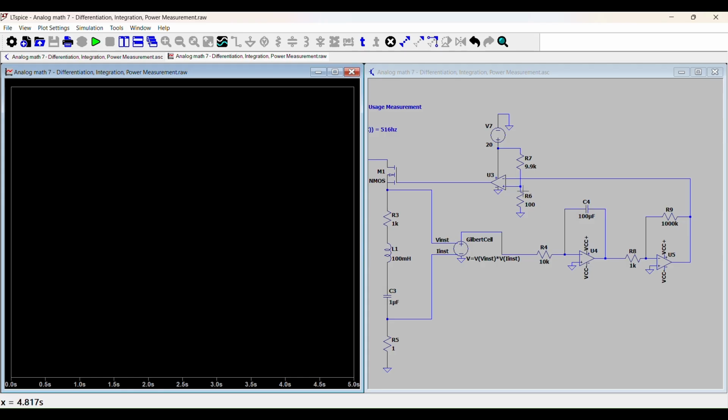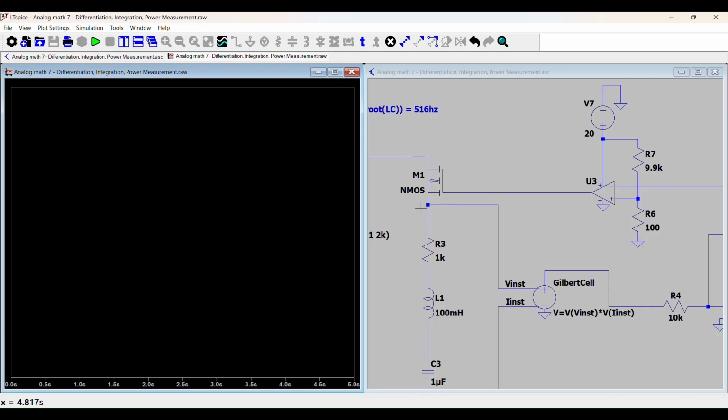You can do this with a much better thing than a voltage divider. You can use a potentiometer here to adjust it, or even a straight signal from an Arduino or something like that. And so this comparator will pull high and low this NMOS MOSFET, to allow the current to flow or not flow. So essentially, after 20 millijoules of energy has been dissipated by the circuit, it turns off the circuit because the gate is going to be pulled to ground.